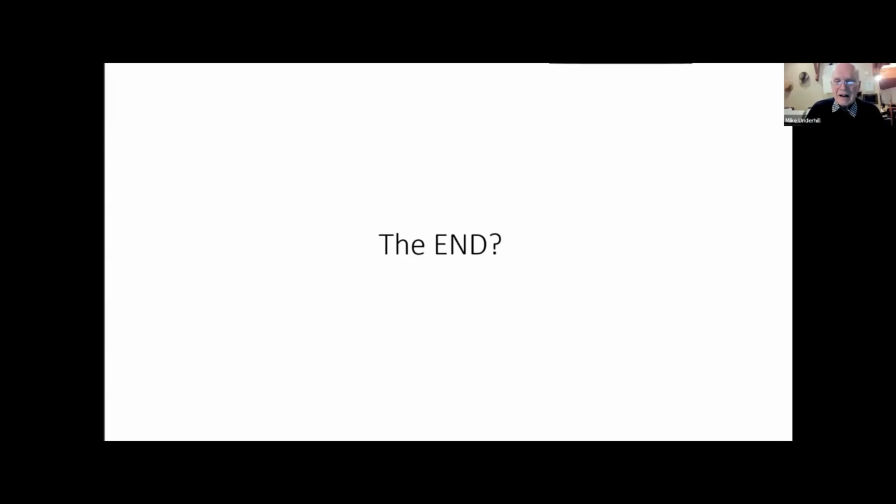Right. The next question from Dave Wellesby: how does the orientation of the mobile affect the antenna performance? But I think you've probably answered that in the time after the question was asked. But is it better to hold it rather than lay it on a table? Actually, holding is a problematic thing as well, because the human body is an absorber. It's a pretty good absorber. So there's a lot of attenuation when you hold something. At 600, 700 megahertz, if you hold the device, you're probably degrading the antenna by 7 dB, roughly. Wow, that's a lot.